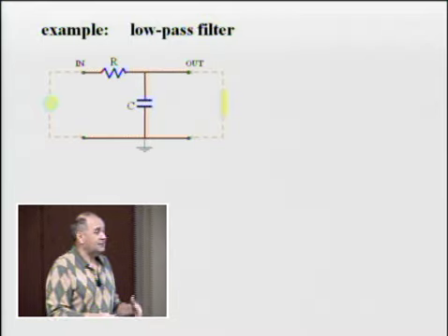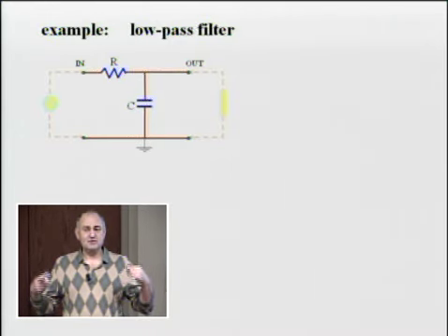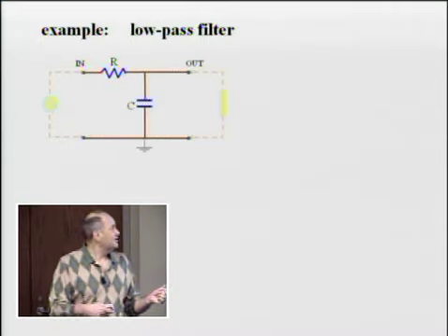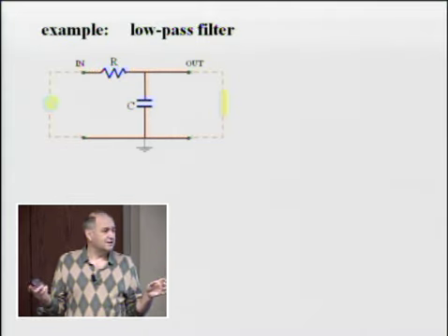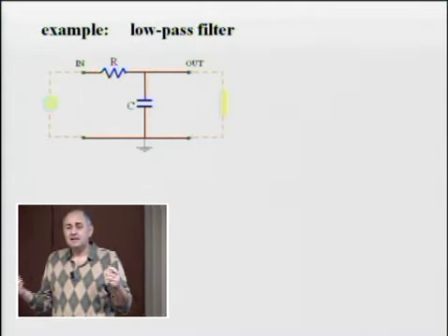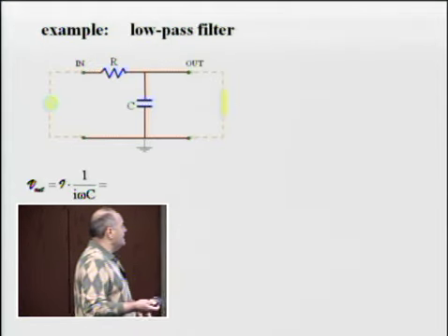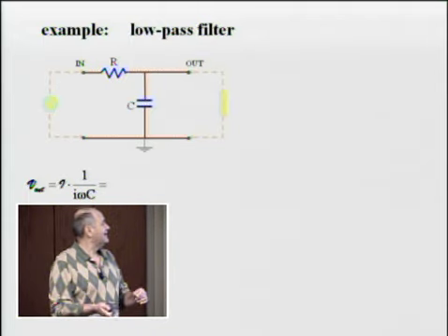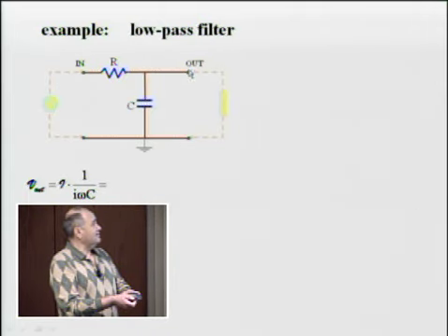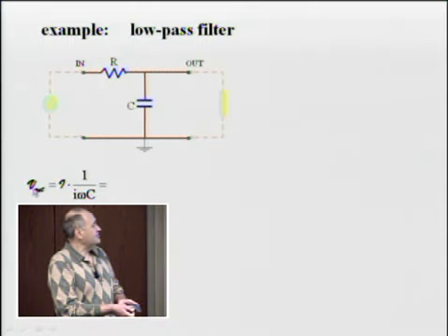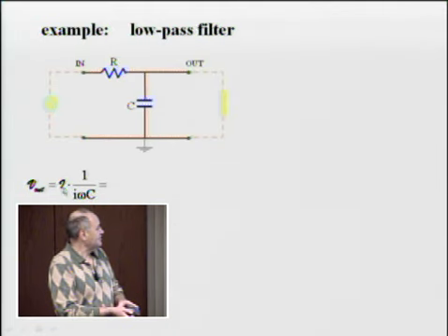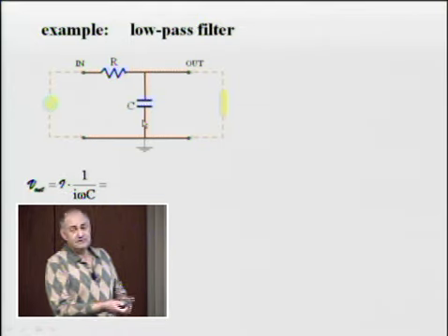Now let's do the same calculations. Let's relate the output voltage with the input voltage, both root mean square value or peak value, I forgot what we related yesterday and what I have on this slide, and the phase angle. All right, so let's start with the complex output voltage. The complex output voltage is the voltage across the capacitor. So the complex voltage across the capacitor is equal to the complex impedance of the capacitor multiplied by the complex current flowing through the capacitor.